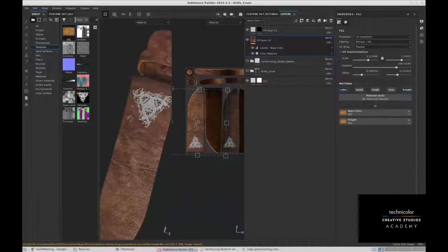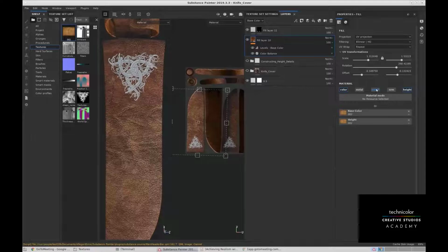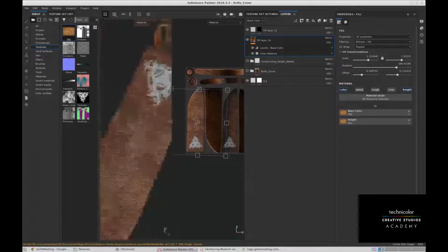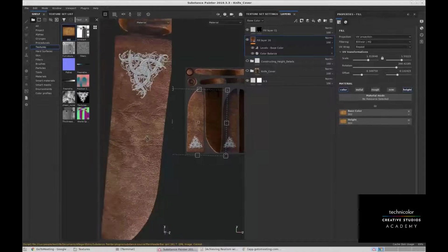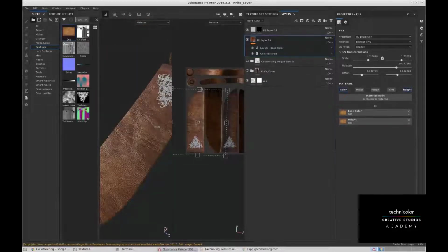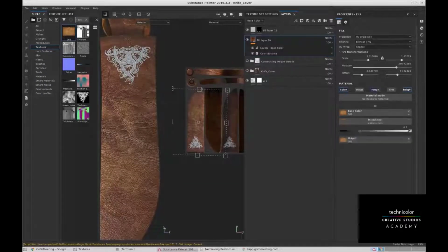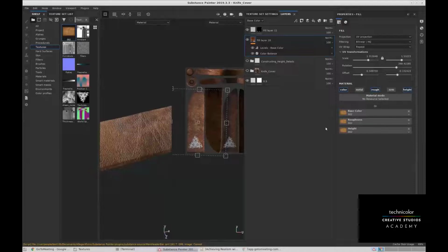In the leather, we now have this roughness channel. Let's say I'm okay with the color and the height. Now I want to tweak the roughness. It's too polished. I guess it should not be like that in real life. So we'll take a roughness channel and just pull out that texture which we use for height and the color map. Immediately you can see the change in roughness.